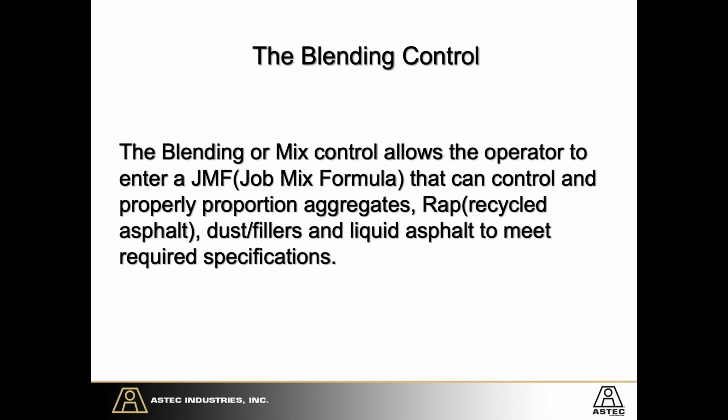Some people ask, what's a blending control? The blending or mix control allows the operator to enter a job mix formula that can control and properly proportion aggregates, recycle, asphalt, dust fillers, and liquid asphalt to meet the required specifications.